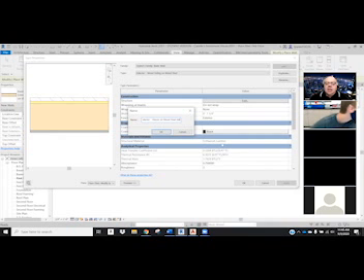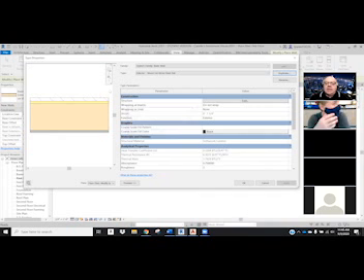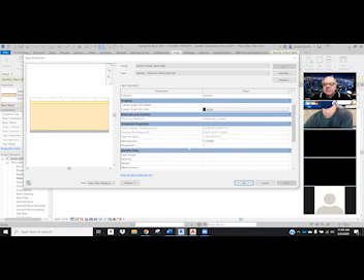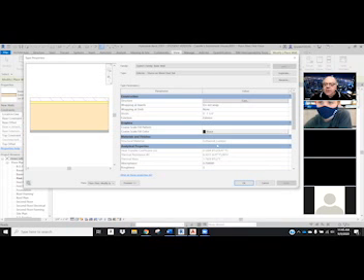Okay. Now, as we hit OK, then everything's kind of changed. We should see the name on our exterior wall here. And again, we're keeping exterior so we can find them easier. Now, the next thing we're going to do is go over here to the structure portion in our parameters. There's quite a few things down there. There's a texture to it. Most of this deals with the 3D rendering aspect of our wall, and we'll mess with that later. But right now, I want you to click on structure and edit. I'm going to edit the structure.